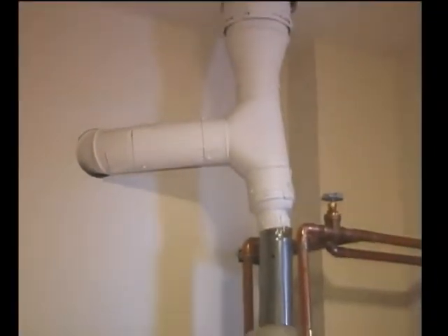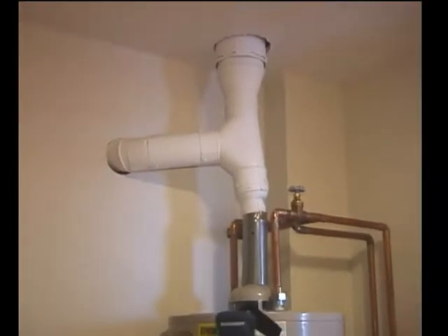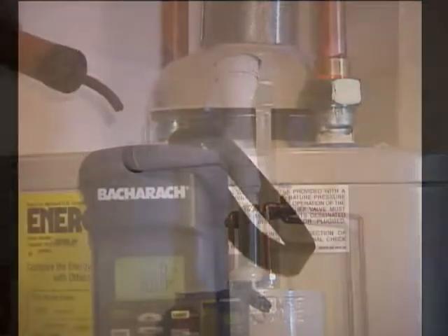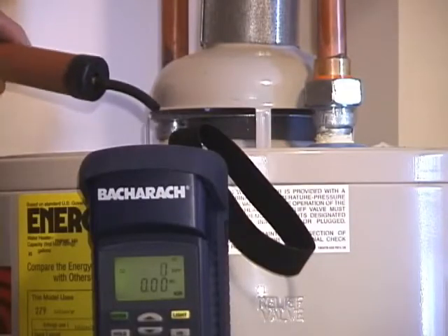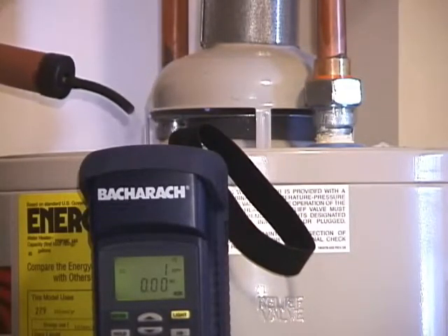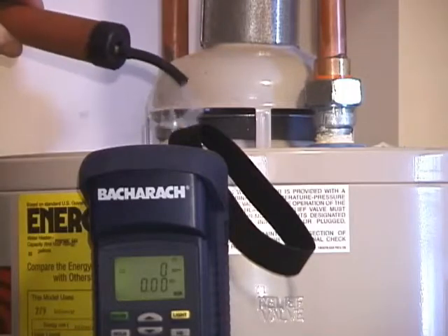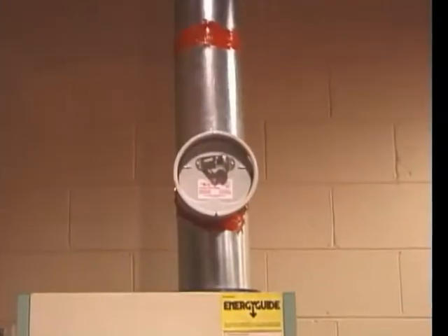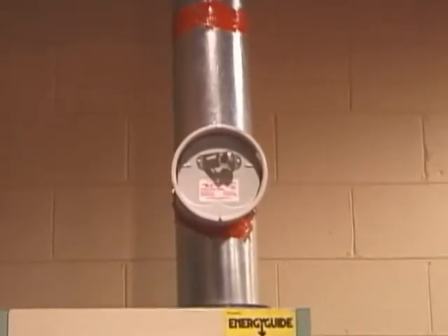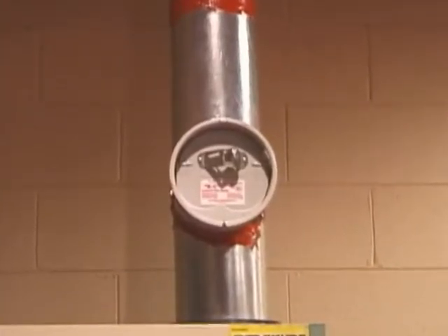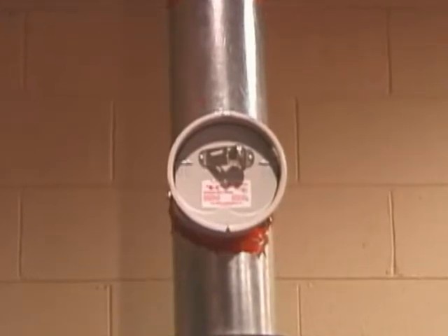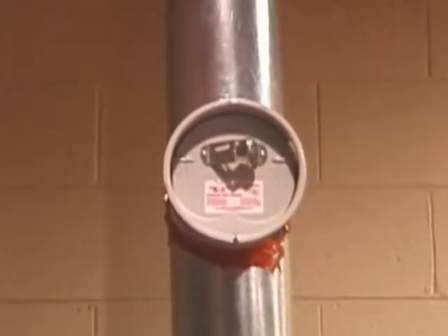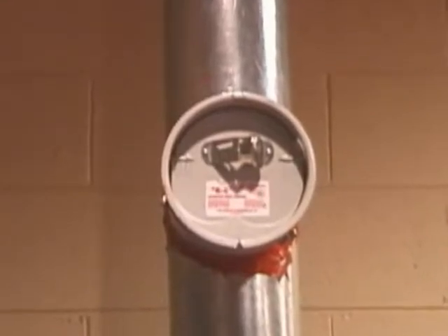And remember that if the furnace with a fan inducer is common vented with an atmospherically vented water heater, and a backdrafting or blocked chimney situation occurs, both the water heater and the furnace's combustion byproducts will spill out through the water heater draft hood. Oil furnaces and boilers typically have barometric dampers that make them less prone to spilling combustion gases to the inside. However, these units can often cause soot and odor, and sometimes cause noise complaints as well.